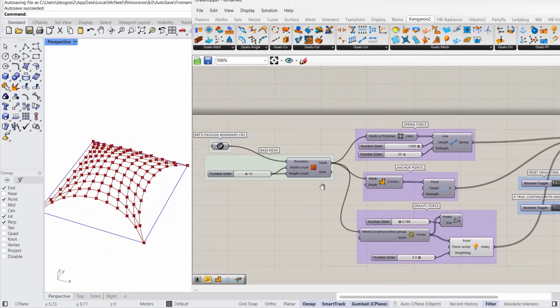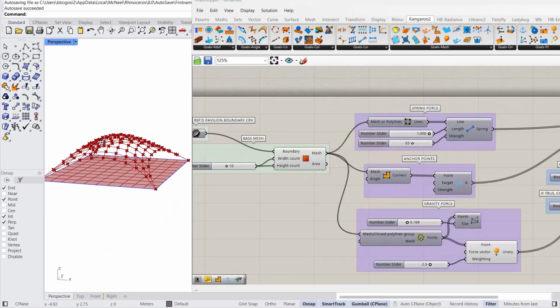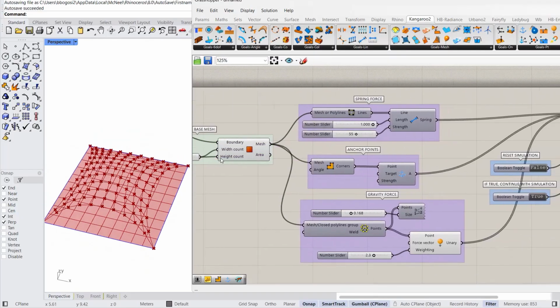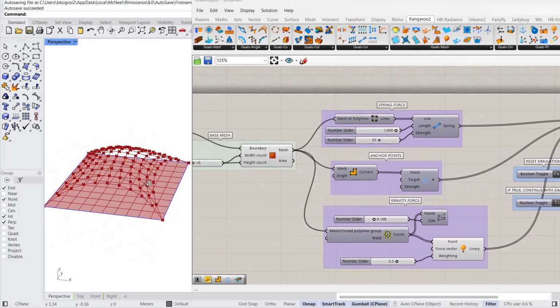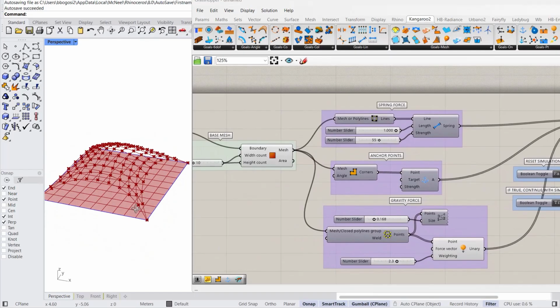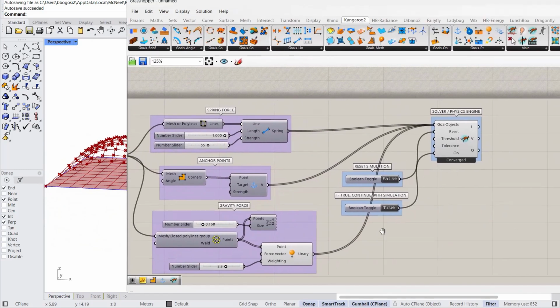Okay. Then let's try to also look at other things. If you recall, for instance, our original geometry that we had was a mesh. So we took from the mesh the edges, the points, and we're simulating it so it works. It's exciting, but it is not returning a mesh. So how do I take that and turn it into a mesh, right? So how do I recover the faces? So by default, it is simulating particles and lines.